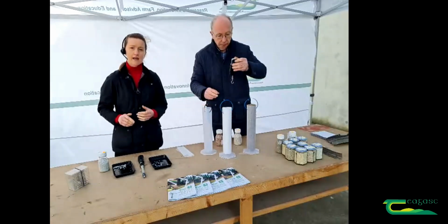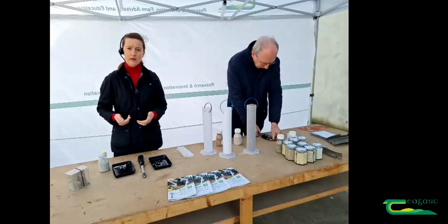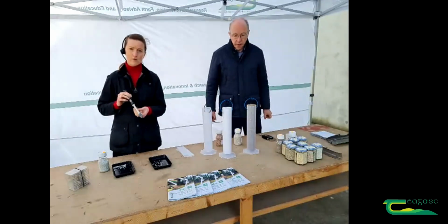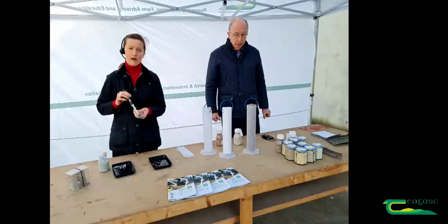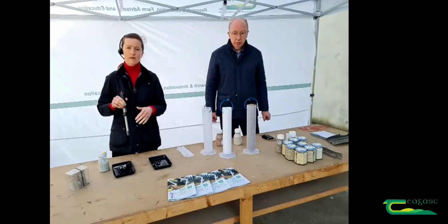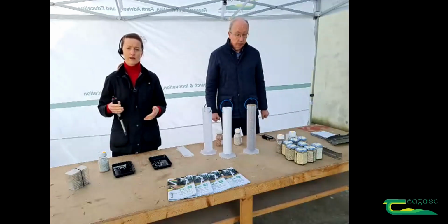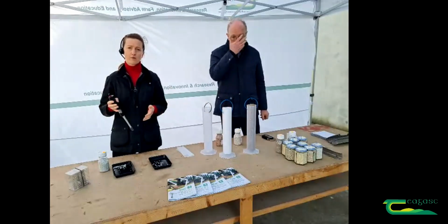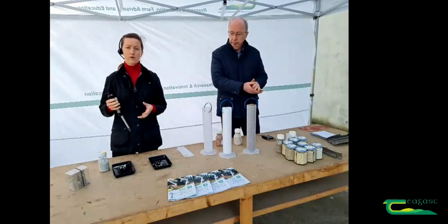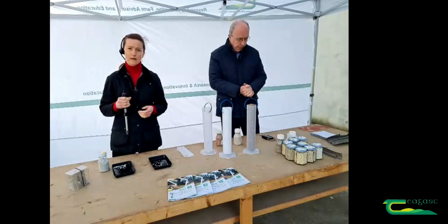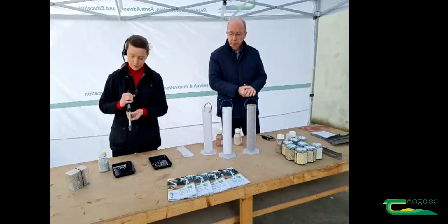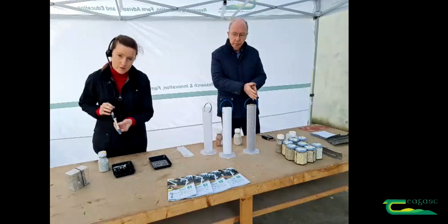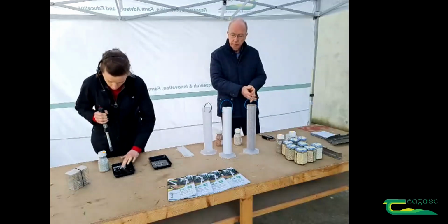When you look at the strength of the fertilizer, we've got this strength tester here, and what we're looking for is that we can score a 6 or over. The reason strength is important is that when the fertilizer hits the vane of the spreader and travels sometimes 24 plus meters, you need a good strong fertilizer to carry through and land that 24 meters or over. I've got the ring here, and when testing the strength, we're looking for a score of 6 or over.